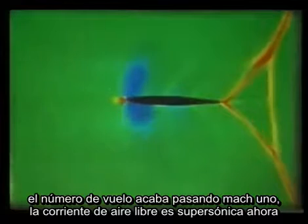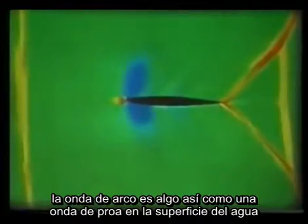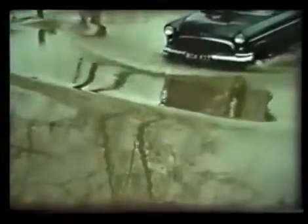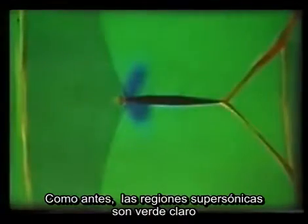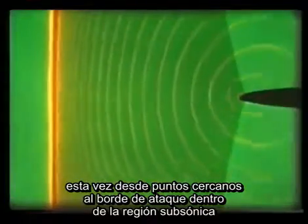The free air stream is supersonic now, and another shock wave appears in front of the wing, the bow wave. It's something like a bow wave on the surface of water. As before, the supersonic regions are lighter green. Like the shock waves on the wing, the bow wave is formed by the constant piling up of pressure waves, this time from points near the leading edge inside the subsonic region.